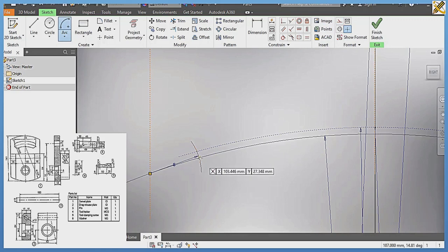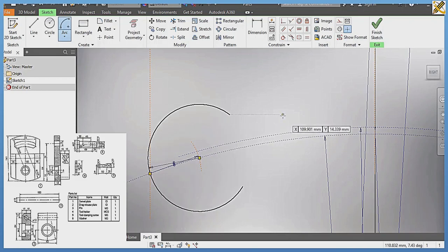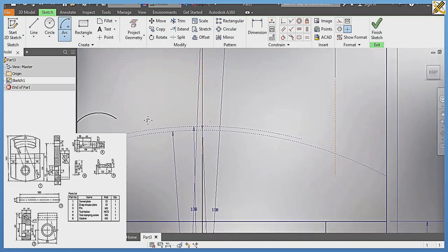Alright, then coming right here in this manner. Going to draw an arc of radius 8 like this. Enter, and I'm going to draw this fully. Okay, that's been settled. So picking my hidden line, coming right here. Radius of 8.